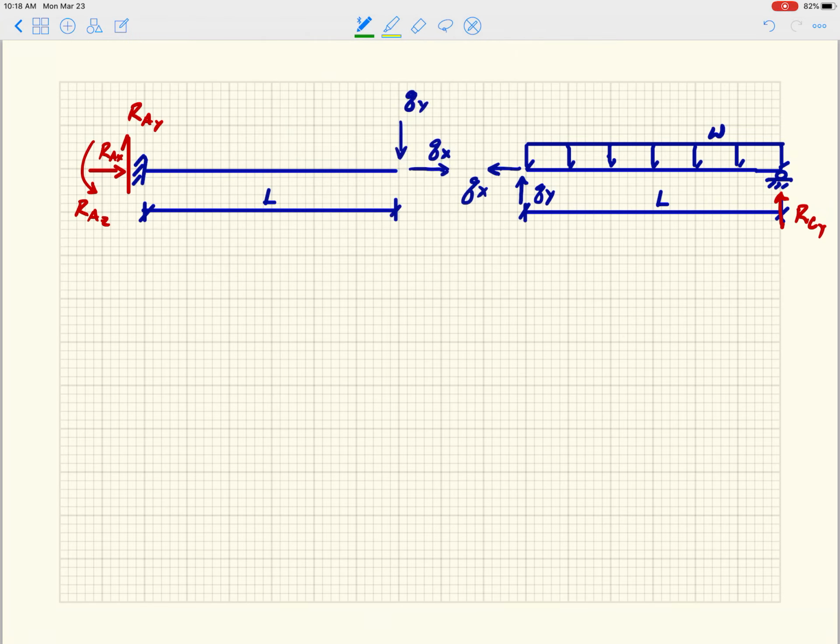So this is x1. This is moment of x1 and shear of x1. Again, those follow our local sign conventions, right? So our local sign convention, we've defined it before. That's why we put the shear force up when it's on the left-hand side. Moment is always compression on the top, right?